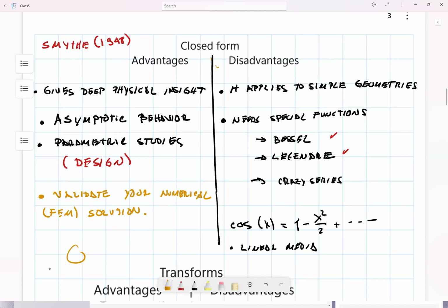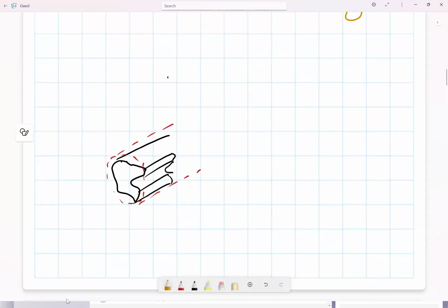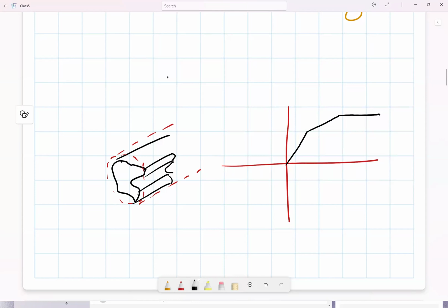Let's say in particular, when you're dealing with saturation, let's take only saturation, no hysteresis. That would be even worse. When you're dealing with saturation, and I'm going to draw saturation like this in 3 sections, you need to be very, very careful. I'm going to put it symmetrical over here. I don't know if I can do it exactly symmetrical, but let's say that it is symmetrical. So you need to be very careful with this, whether you are in the first linear section between this point and this point, no problem, right?